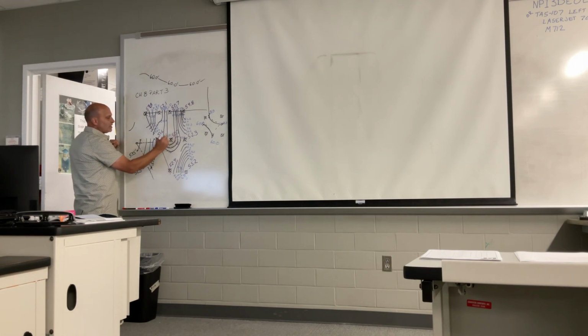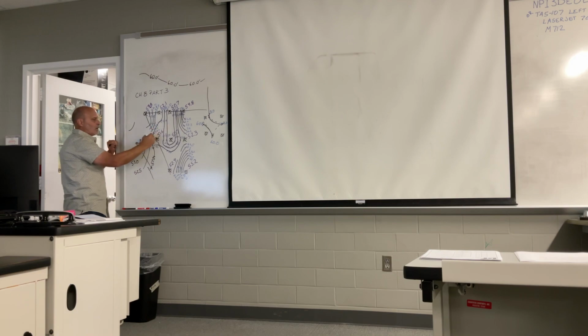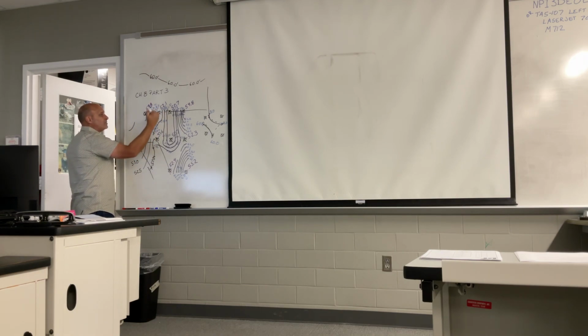So if I had this tick mark right here, and I'm making that contour like that, when I leave this one right here, I'm gonna probably pick out there outside, because remember, we always run it outside, because we know we aren't cut off at a cliff's edge right there. So I might pick a point out there, and instead of going straight down to this next tick, I'm gonna pick a point there, a point there, then a point there, pick a point here, then pick a point there, here, then pick.